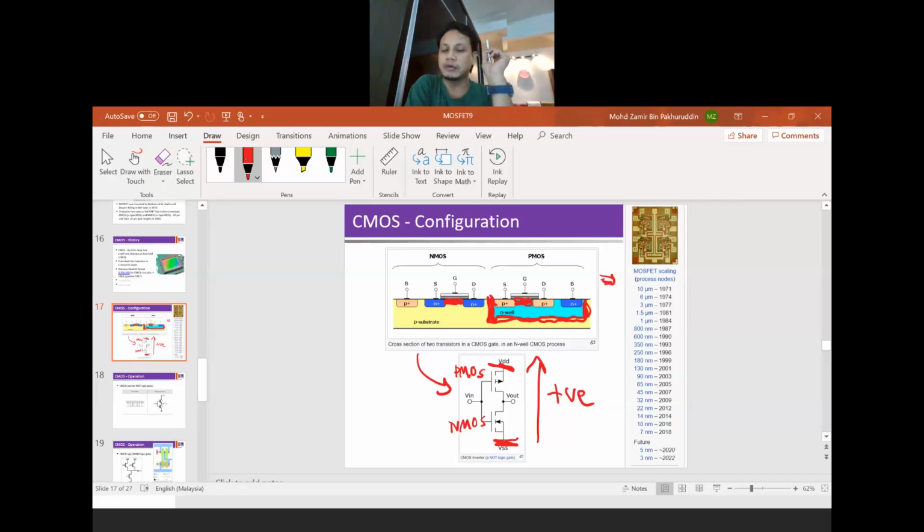It's on MOSFET scaling. So back then in 1959, 1960s, the gate width was around 10 micron, 20 micron. So you can see here, as the time goes on, from the 70s up to now, the industry has gone down to really small gate width. So up to now we have around 5 nanometer by IBM, and TSMC is planning for 5 and 3, will be in production soon. So it's gone down from tens of microns to only a couple of nanometers, right?